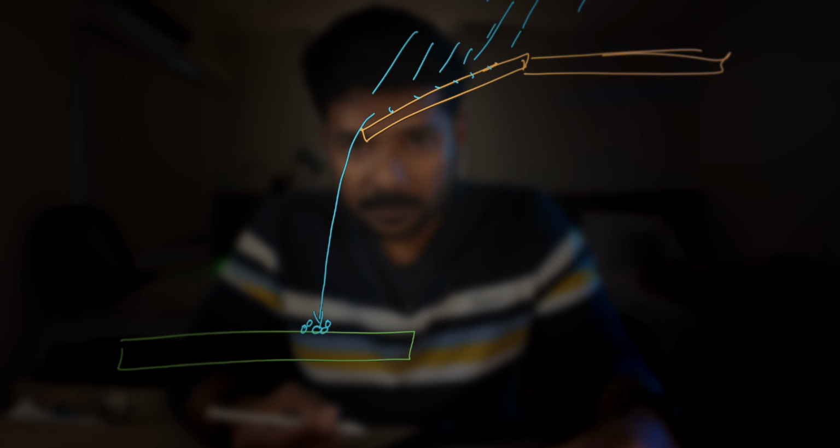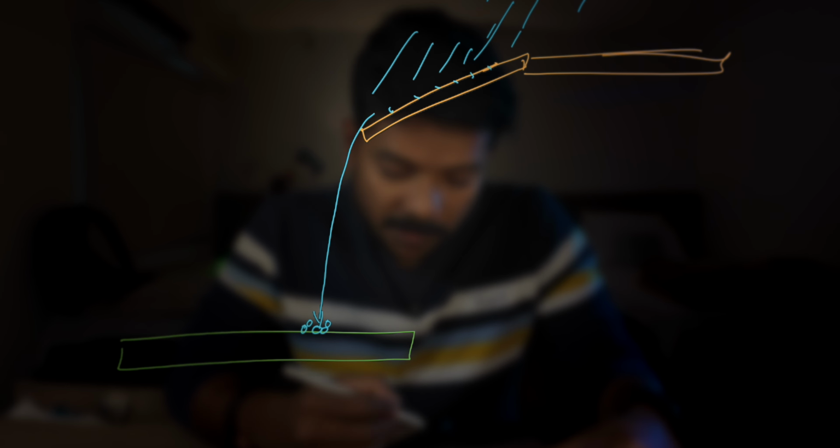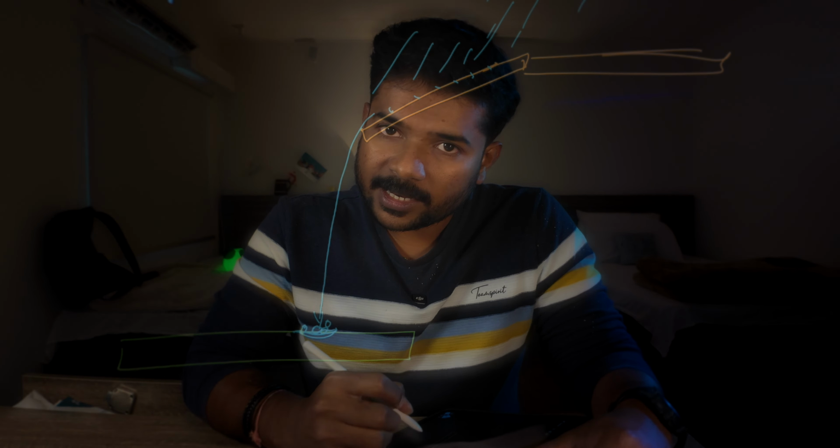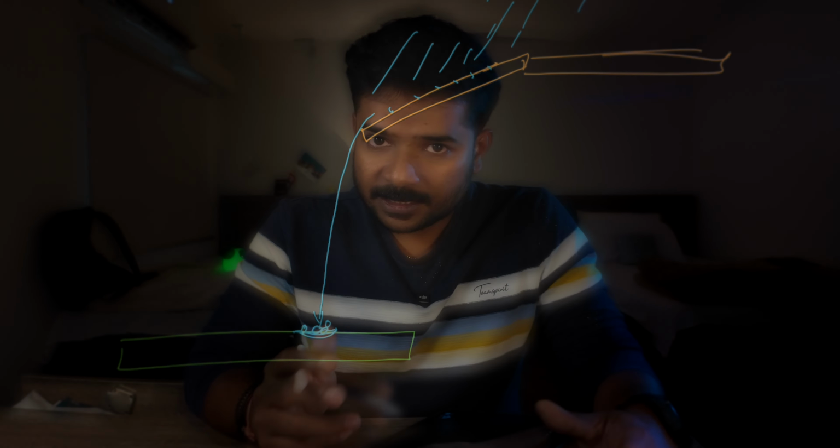So what happens is, when rain falls on copper, this rain droplets might break out small particles of copper, and then this rain falls onto aluminium cladding. And where this rain falls, the rain droplets brings copper, and this copper along with water touching aluminium forms the battery, and thus the corrosion. Here corrosion begins, and, well, this is a rare case, but if these conditions are met, you will see white aluminum oxide forming where the water falls. This is another case of bimetallic corrosion that may happen in facades.